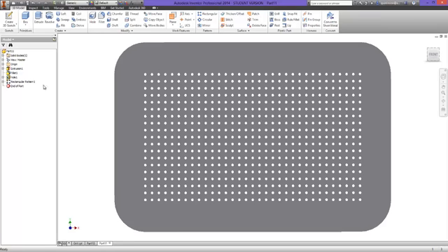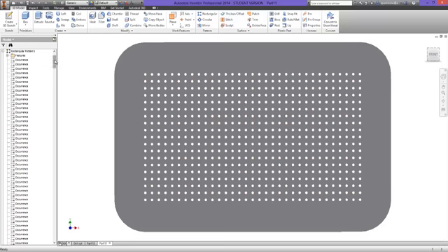Next thing what I'm going to do is open in the model tree the rectangular pattern, and you'll see there's occurrence. This occurrence just basically means where each hole occurs on the face. So I'm going to go ahead and find the holes that I want to hide in order to put my volume control hole in. So if I just select them three, right click and suppress, you'll see that they disappear from the front of the model. And then I'm just going to go up another 17 notches, right click, suppress, and I'm just going to do the same process one more time, another 17.